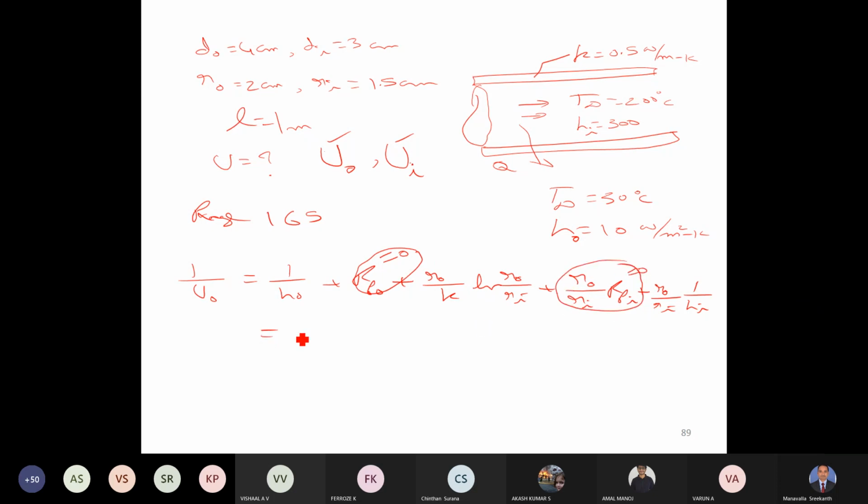So what remains is 1 by H naught plus R naught by K log of R naught by RI plus R naught by RI times 1 by HI. Okay.